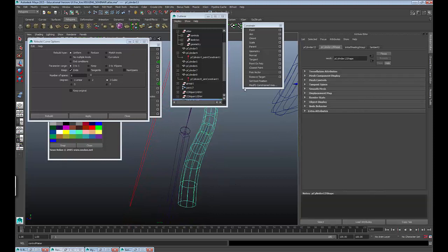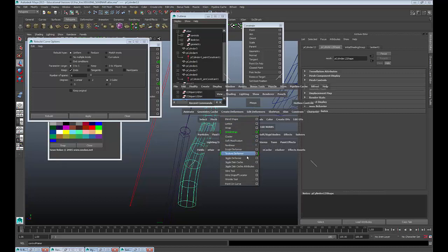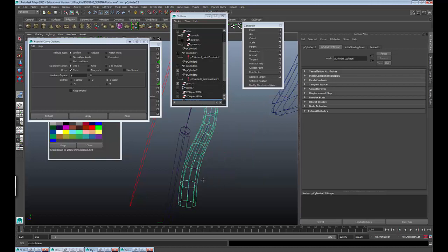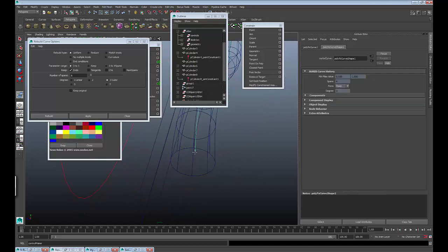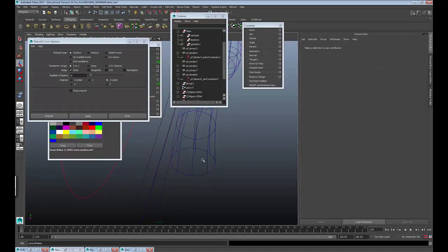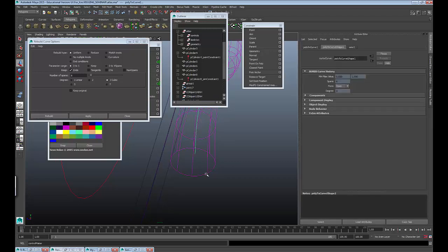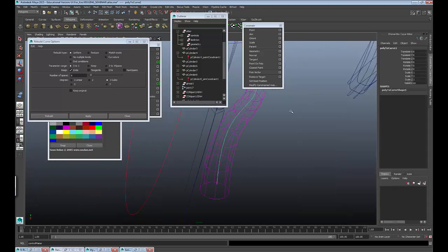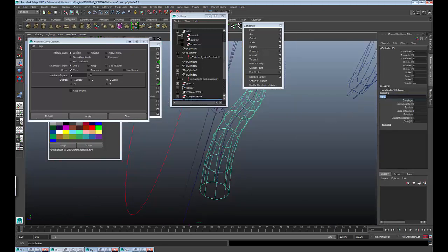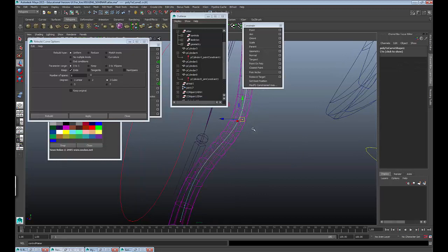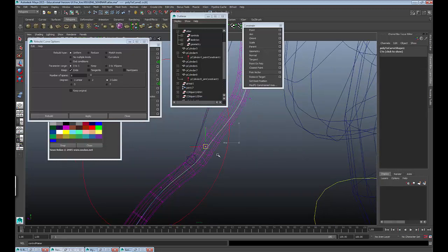So the wire tool is create deformers, wire tool, hit enter because the geometry is selected already. Select the curve, hit enter. There you go. In wireframe, you can see how the geometry turned pink when that curve was selected. That means the connection's there between the two. And again, under the wire, we're going to increase the drop-off significantly. So now we have fewer points to control that mesh.